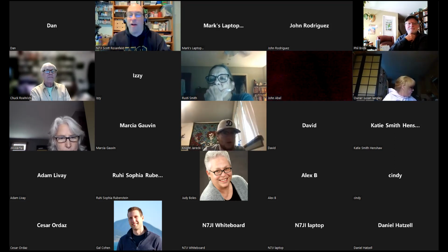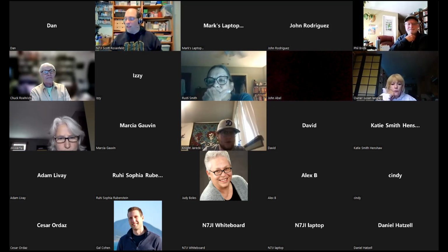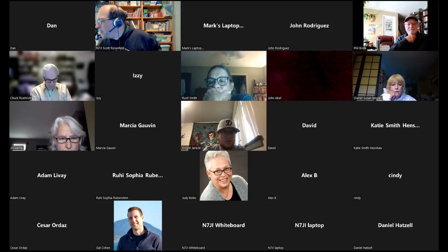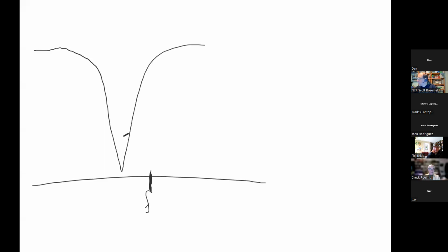That little bit of rounding is not a big deal, and here's why. Let's say that you have an antenna, and we're going to make this antenna, and we're going to draw our frequency chart, and our target frequency is right here. We want our dip in our antenna SWR to be right there. And we say, okay, well, it actually looks like this. So our antenna is obviously working best at a frequency here, where here's 0, here's infinity. The frequency is too low.